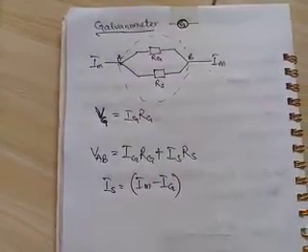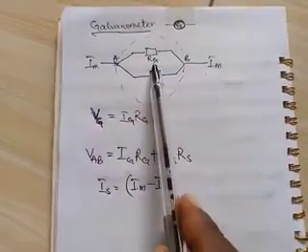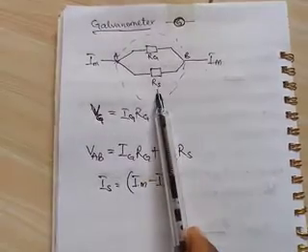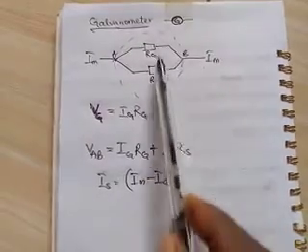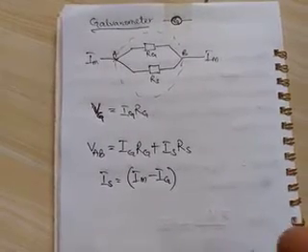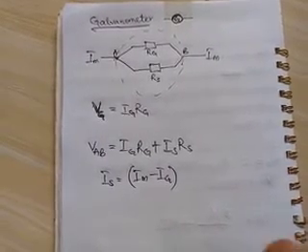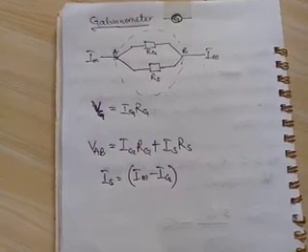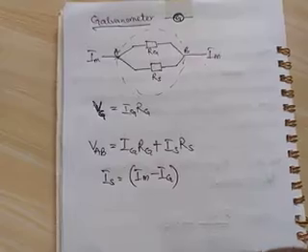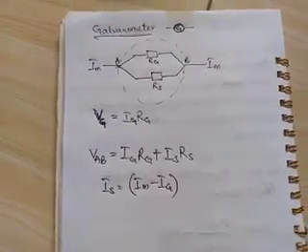You need to note that since the resistor of the galvanometer and the resistor of the shunt are in parallel, the voltage in them are the same. An ammeter has a very low resistance and it is also connected in series with the circuit, which means you have to break the circuit to insert the ammeter.